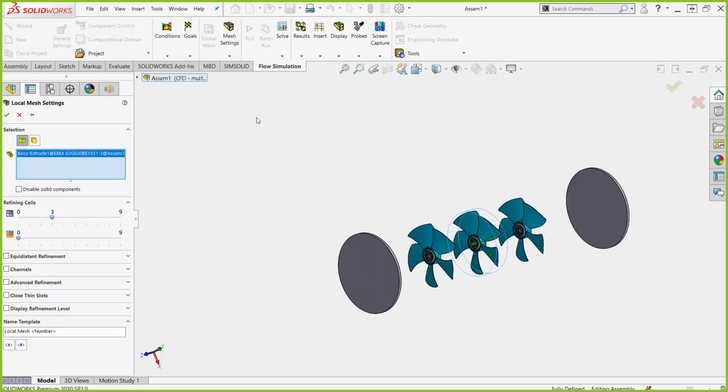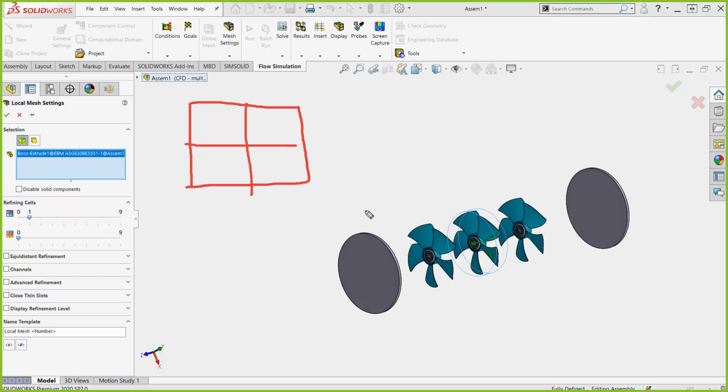I wish I'd had my PowerPoint slide on this, but essentially this is a mesh cell. It's a cube. When I tick this 1 level over, I cut this cube into 8ths. And then I go that 1 more time, and then I cut up into whatever that number is. Over and over. So the mesh blows up very quickly.